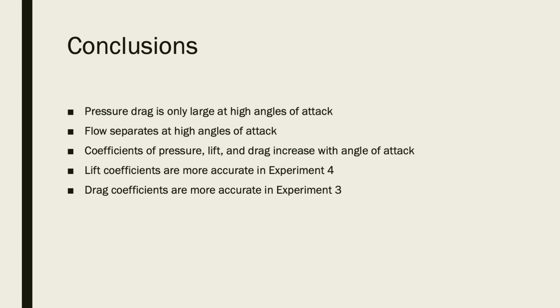Also, it is interesting that the lift coefficients are more accurate in experiment 4. This is likely because the pressure distributions measured by the static taps and pressure transducers are relatively error-free and yield reliable results. However, the drag coefficients measured in experiment 3 match more closely to the NACA results compared to the drag coefficients measured in experiment 4.